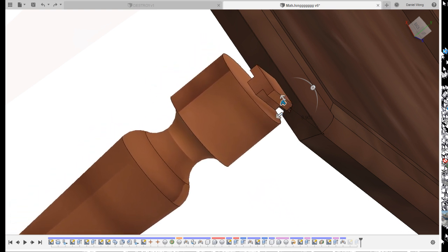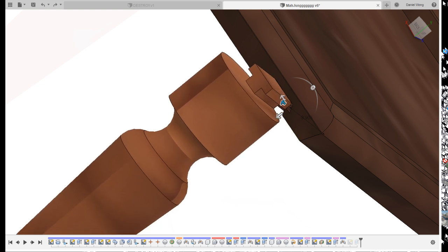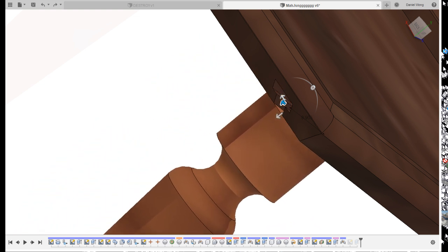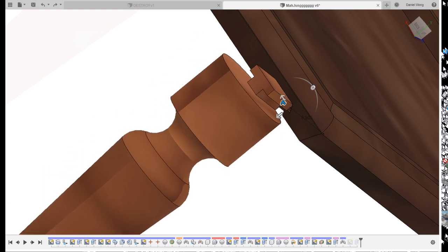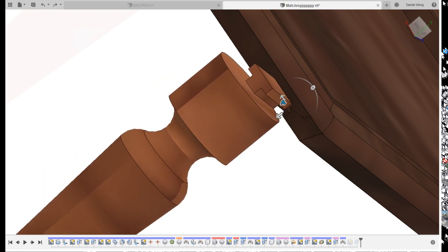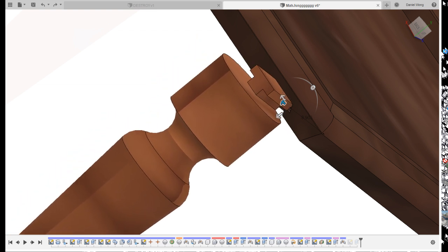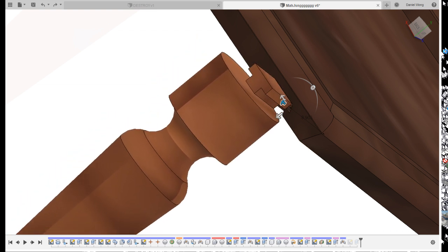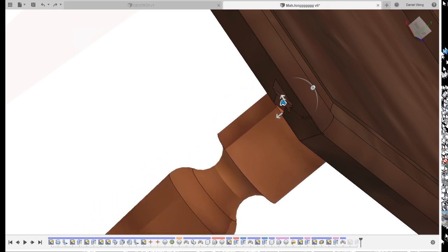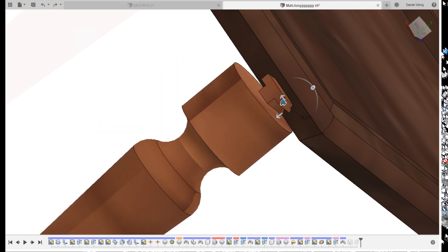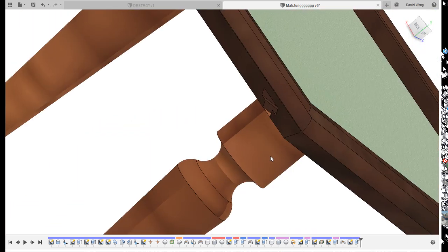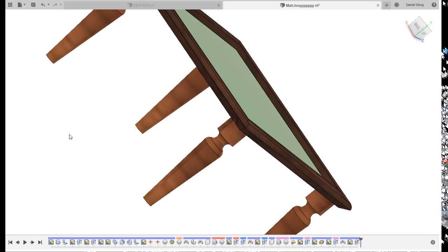But you'll notice that there is 1 degree of freedom here, isn't there? There has to be 1 degree of freedom for this to happen, right? So joints, as I showed you, don't just have to be 0 degrees of freedom, which is when it's fixed, when it's called a rigid joint. We can also apply sliding joints of about 1 degree of freedom in this way. And now there is another sneaky one, which I need to find.